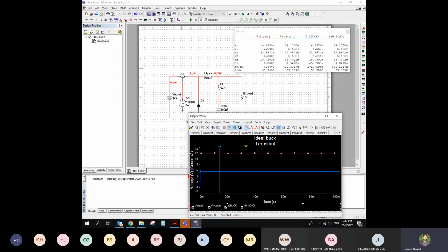But what is changing significantly is the output current. Since the voltage is almost constant, if you change the value of the resistor here, the current will change significantly. Previously the current was somewhere between 1.1 and 1.4. Now it has definitely increased to almost 6, right? 6 volt divided by 1 is almost 6. So the current is going to get affected here.